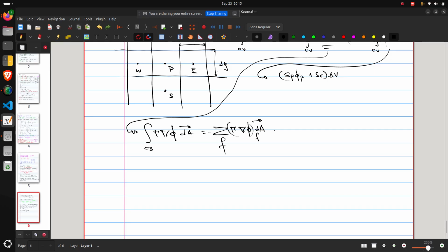And for this kind of structured mesh, we will just have the different faces, right. So, east, west and north and south. So, it is nothing but gamma_e times (phi_E minus phi_P) by delta x, and the area will be delta y, right. For the west face, it will be negative because again the area vector points in the negative x direction.